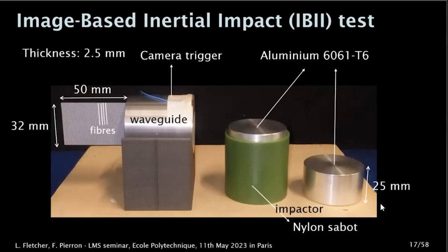So we have the specimen here, which is flat. In-plane dimensions vary depending on what you want to look at. Here, the example I'm going to demonstrate it on is a composite with fibers aligned in the vertical direction. Okay, so it's transverse direction, unidirectional composite. To hold the specimen and also smooth out the introduction of the wave, we use a waveguide, which has also the advantage of holding the specimen. So we put the waveguide on a foam stand. The specimen stands here, waiting to be impacted.